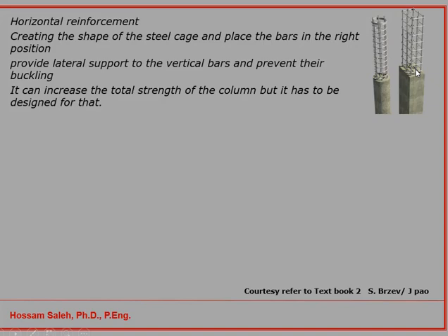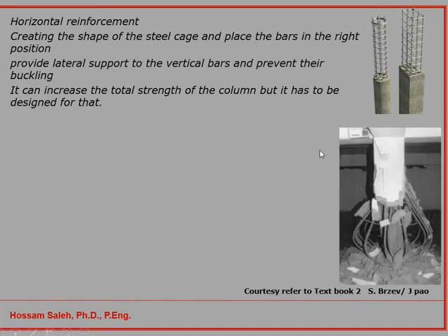It is like confined columns. And if you can see in this picture, that's not part of my PhD; I have that from the textbook. Here you can have the concrete column collapsed after the collapse of the concrete cover, and also the very important one is the collapse of the horizontal reinforcement. So when the horizontal reinforcement cannot support the longitudinal bars against buckling, you have a crack